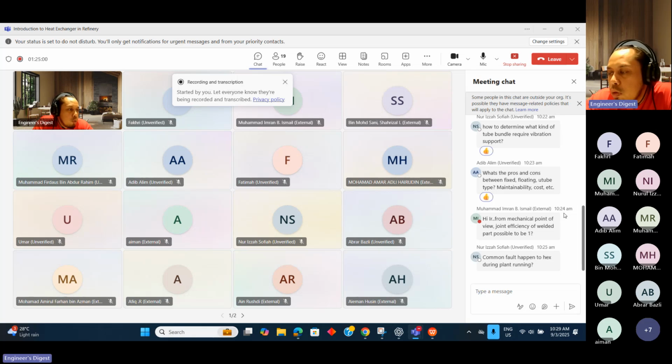Maybe they put it wrongly, so it is rotated one bolt. What would happen is this partition plate will press all of the tubes. The tubes have a bit of extension, like 3 mm. So once they are pressed, we need to plug all of them for nothing actually.